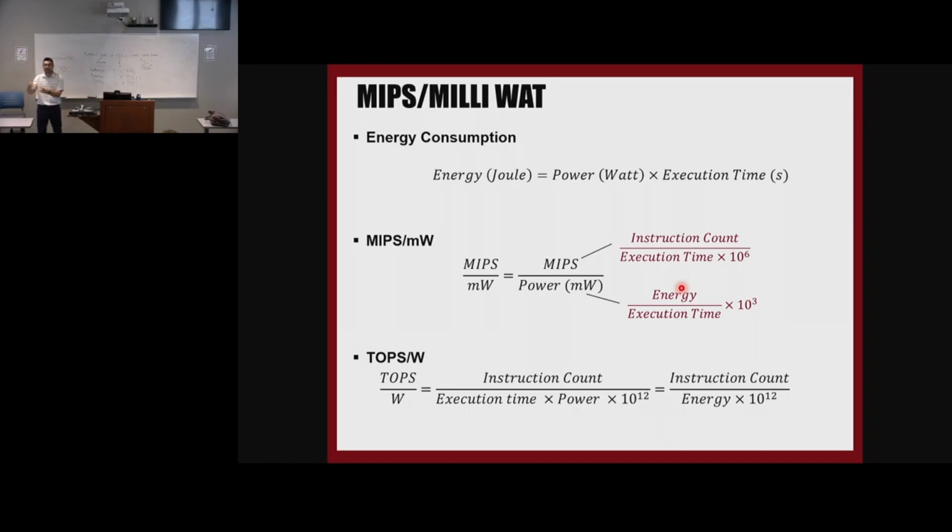We say, okay, we have designed this architecture in our lab, and it achieves 4 TOPS per watt, 64 TOPS per watt. These are the numbers that we're getting these days. TPU can achieve something around 2 TOPS per watt right now, 2 trillion operations per second per watt at best.